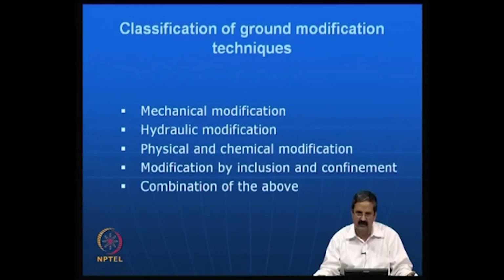The advantage is that whatever load is on the soil is now taken care of by the friction between the soil and reinforcement. Because if you apply load, the load gets transferred to the reinforcement and soil, and there is friction between the soil and reinforcement. Because of this friction, that particular component will help in taking the extra additional load.